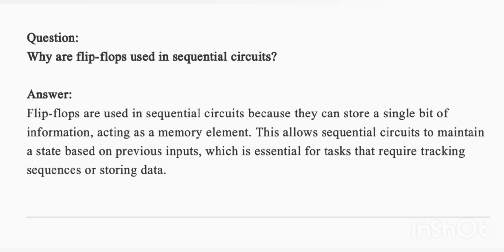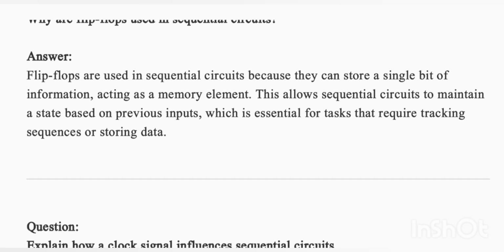Question: why are flip-flops used in sequential circuits? Answer: flip-flops are used in sequential circuits because they can store a single bit of information, acting as a memory element. This allows sequential circuits to maintain a state based on previous inputs, which is essential for tasks that require tracking sequences or storing data.